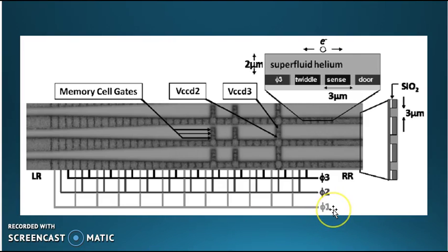A set of 3 gates, known as the clocking voltages, are voltages 1, 2, and 3. Each of these 3 gates defines one CCD, or charge-coupled device. This is called a pixel. For example, these 3 represent a pixel, these 3 are another pixel, etc.